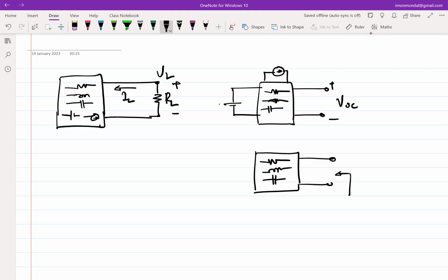And when you are trying to find out the impedance, what do you do with the sources? Sure. You have to de-energize them, which means all the voltage sources will be nulled and all the current sources will be open. Mind you, these are all independent voltage sources and current sources that are being nulled and opened. If there are dependent sources inside, they remain as is. So all the independent current sources are open and voltage sources are shorted. And we are trying to figure out what is the output impedance.